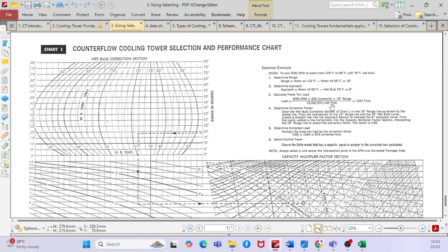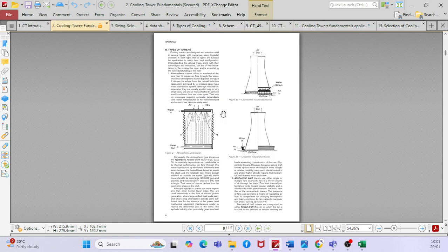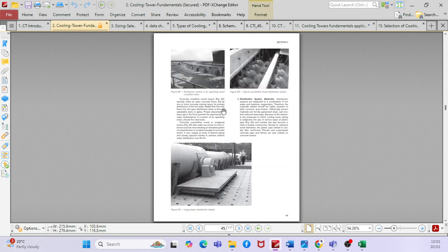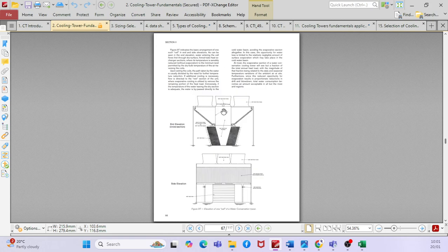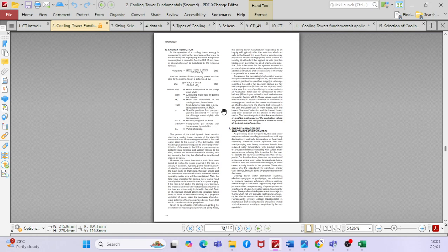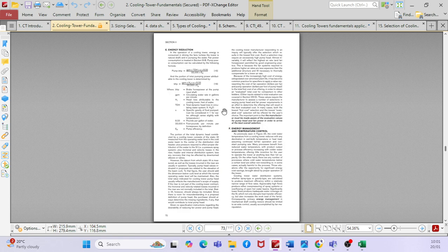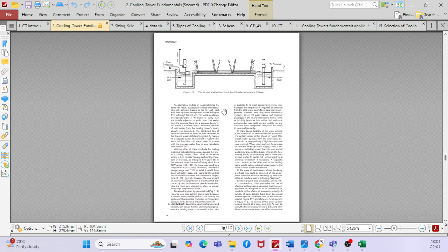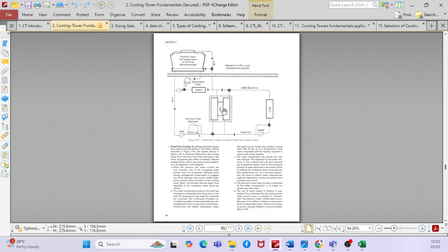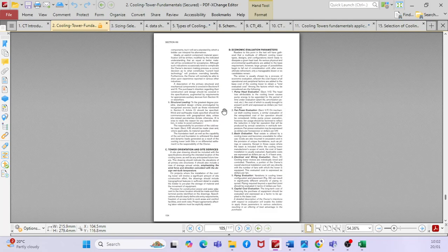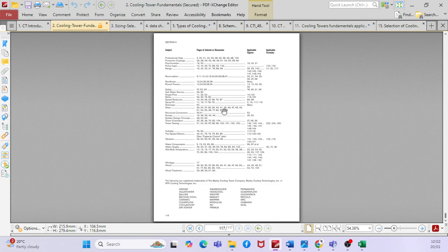Clear, right? This is the equation. This also we have to say in ton. If you go through this handbook, even for cooling towers it has a different tonnage. Yes, cooling tower has a different tonnage, that is 15,000 BTU per hour. Because I was thinking it's the same as your cooling load essentially. That's what I wanted to confirm.